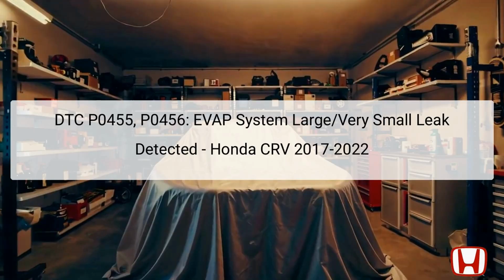This presentation focuses on the DTC codes P0455 and P0456, which indicate a problem within the EVAP system of the Honda CRV models from 2017 to 2022. DTC P0455 refers to a large leak detected in the evaporative emission control system, while DTC P0456 indicates a very